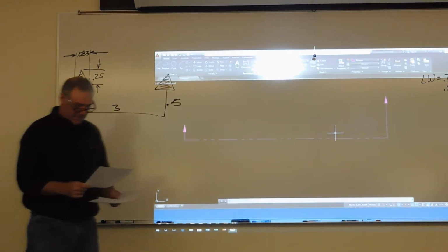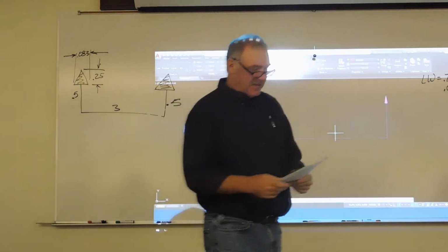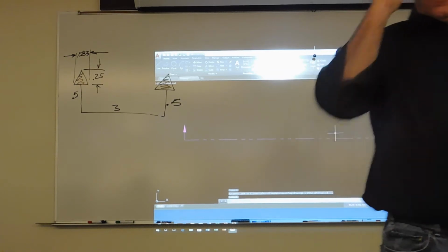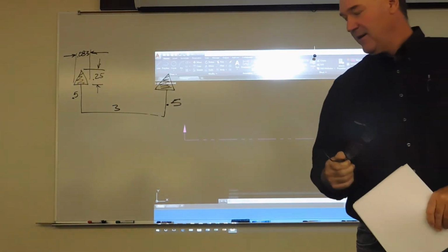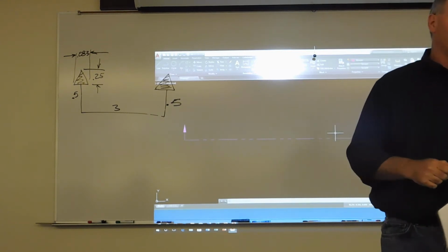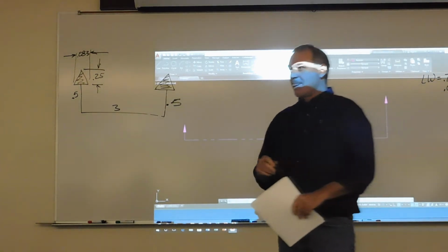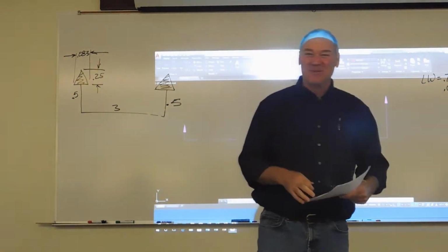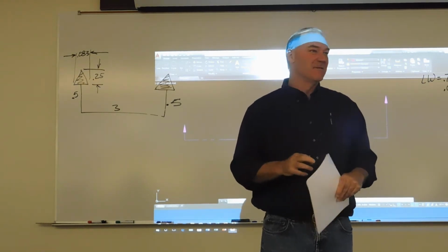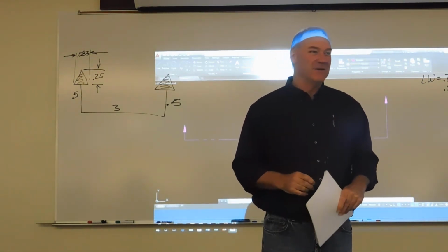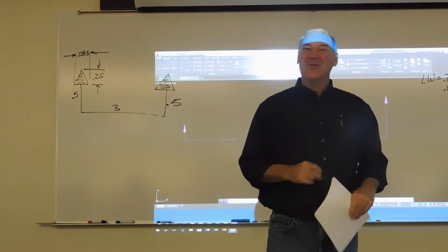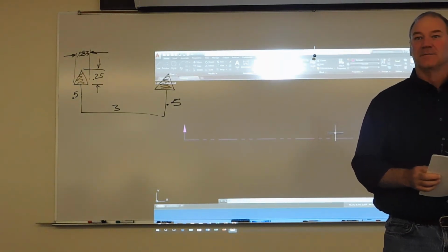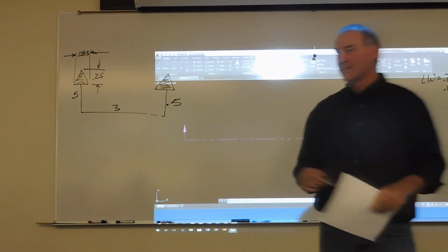All right, now there is one caveat on cutting plane lines. It says in the text that the location or the cutting plane line may be omitted if the location of the cut is obvious. That's true, but I want us to have practice drawing cutting plane lines and putting them where they're at so they visualize it. So for us, for the next week or so as we do section views, that is not true for us. We'll do section lines on every drawing we do, at least for the next week or two. Okay? And then we will stop them after that when the location's obvious.